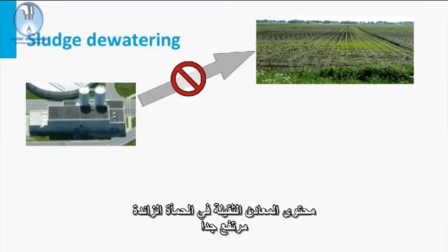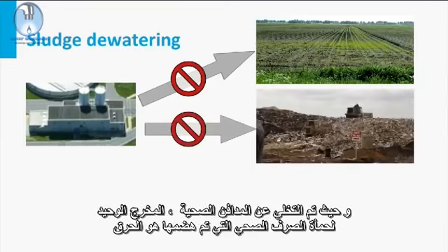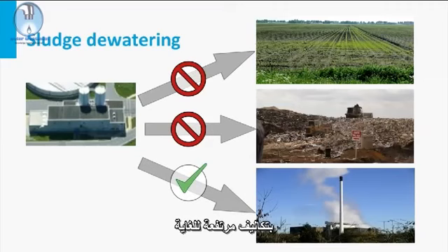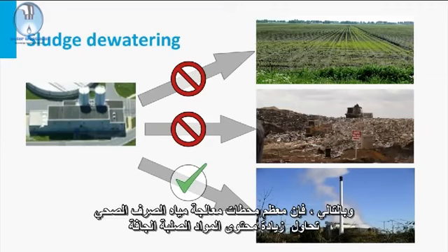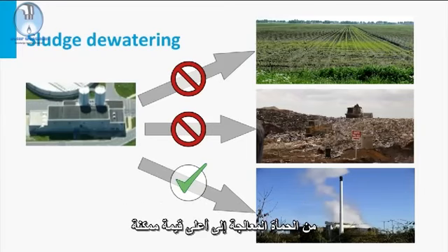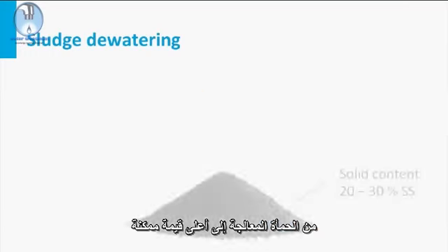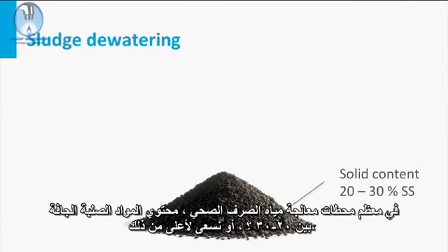The heavy metal content in the excess sludge is too high. Since landfills are abandoned, the only outlet for the digested sewage sludge is incineration at extremely high costs. Therefore, most sewage treatment plants are trying to increase the dry solids content of the treated sludge to the highest possible value. In most sewage treatment plants, a dry solids content between 20 to 30% or even higher is pursued.